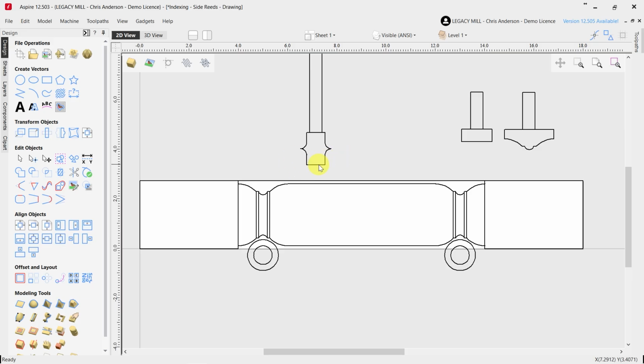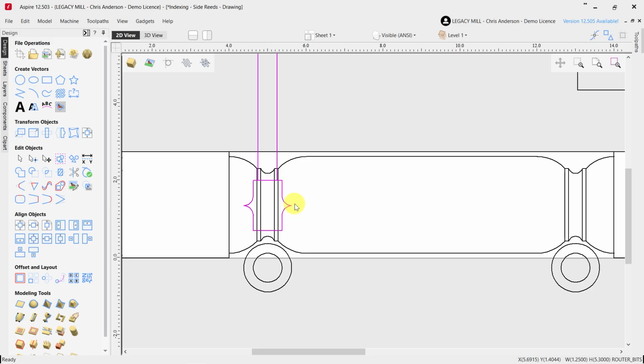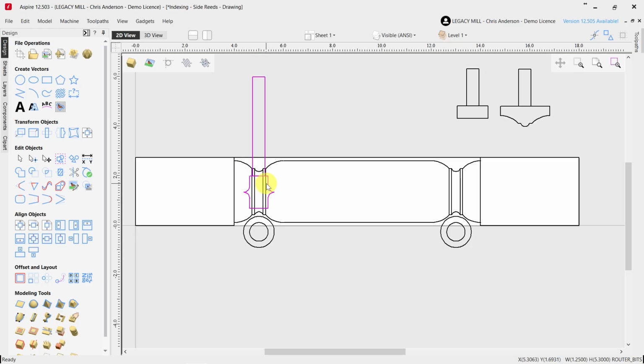This tool is going to start at a location and plunge along the edge of the spindle. So it's not on the top center of the spindle like all the other toolpaths. It's on the edge of the spindle, and it's going to line up the center of this profile radius, that round over profile, until it puts the tip of the cutter right in the center of the spindle, again from the side. Then it's going to travel all the way down to the ending position, then lift up, and it's done with one read.